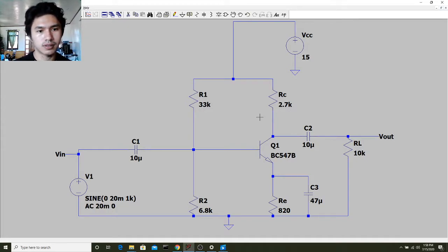The circuit I made is what we call the common emitter amplifier circuit. It is a circuit that has a resistor in its collector circuit. In this circuit, the current that flows through this resistor produces the voltage output of the amplifier. This circuit also uses what is more commonly called voltage divider biasing.